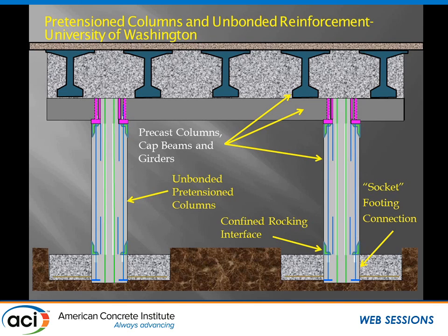So it's an interesting combination of the fact that you get the advantage of being able to make these in advance. You get the advantage that they're pre-tensioned, okay? They have an active axial force on them, but you don't have the problem in the previous case where you had those concentrated strains and a large crack occurring because the system wasn't unbonded. So in this case, the post-tensioning is unbonded.